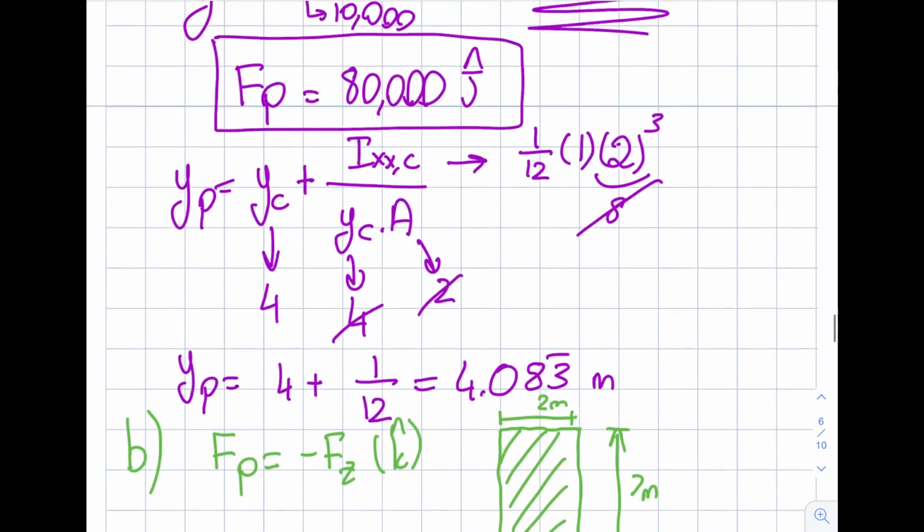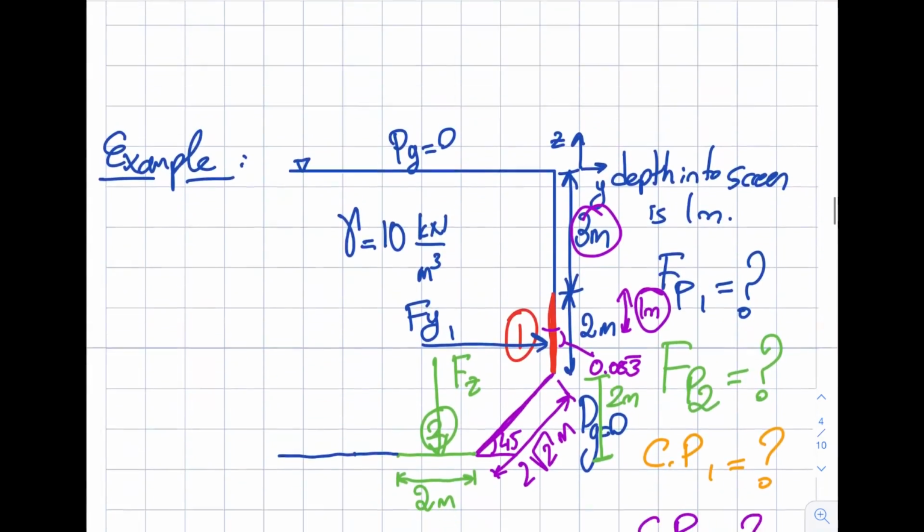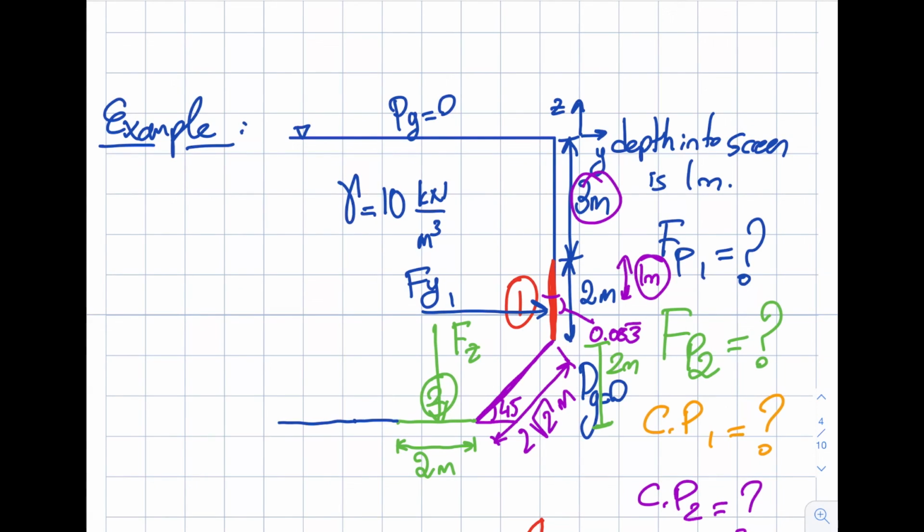So the next question is center of pressure. Where is this acting? Well, that's actually the easiest question kind of ever, right? So it's acting in here, right? 7 meters from the surface. And you can see it's going to act right in the middle, right? And if you have into the page, it will be 0.5 because it's still a rectangle.